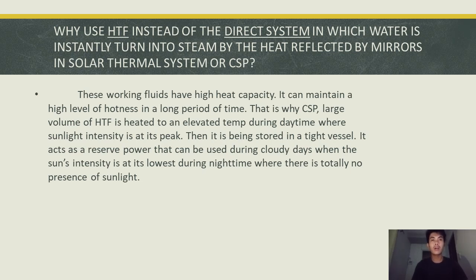The cost associated with increased fluid makeup rates, the downtime required for heat transfer fluid related maintenance, and lost heat transfer efficiency due to degradation byproducts have to be strongly considered when choosing between a lower cost fluid that will be bumping up against its maximum recommended use temperature and a more expensive fluid that will fit nicely right in the middle of its operating range.